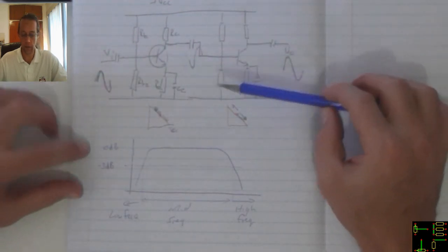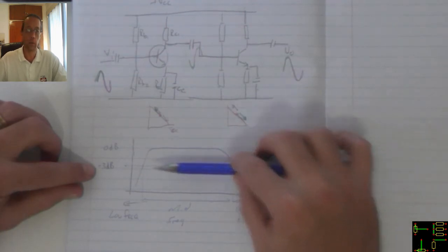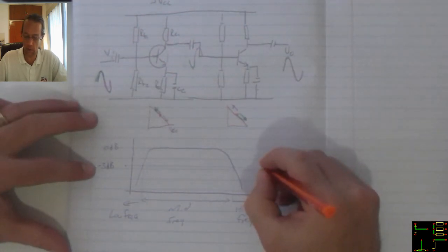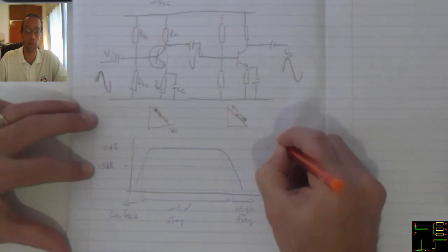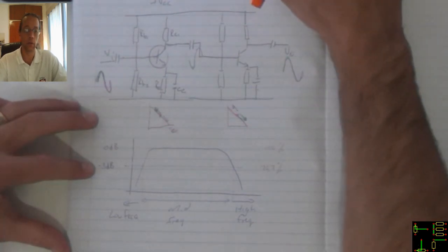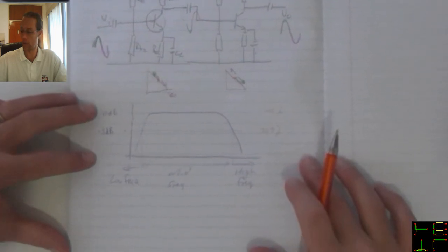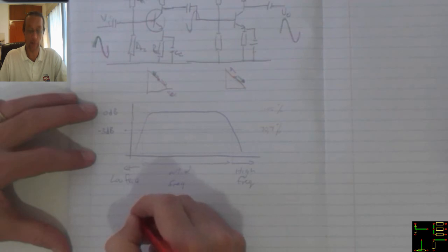Okay, I've mentioned the -3 decibel level is my half power level, and at that level we will have 0.7 or 70.7% of full power. Anything below that we consider losses. And when it comes to calculating the gain of my RC amplifier, if I want to calculate current gain,